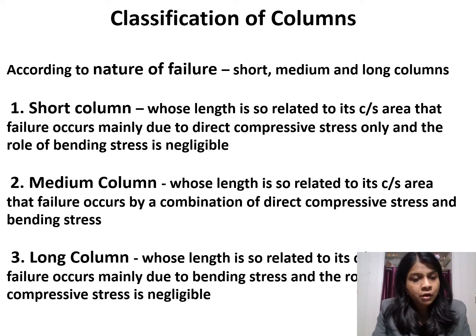And in case of a long column, the column will fail due to bending only. The bending stress will develop before the compressive stress will be developed inside the column.